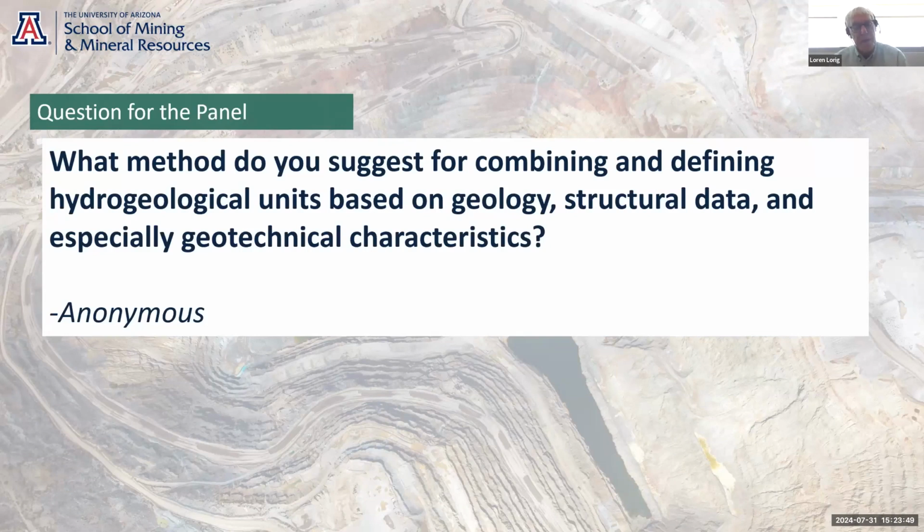Yeah, so I'll just add to that, Jeff, that the blockiness is governed by the fracture frequency and RQD. The joint condition also can play a role depending on how the joints are filled or how planar they are, what their characteristics are. So those two things, which are the primary geotechnical characteristics, the blockiness and the joint condition, probably have a role in defining conceptual units for further development.